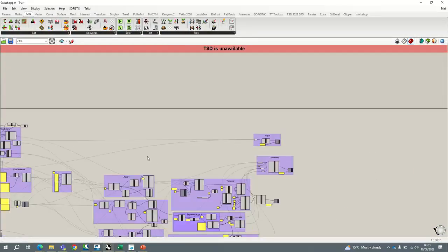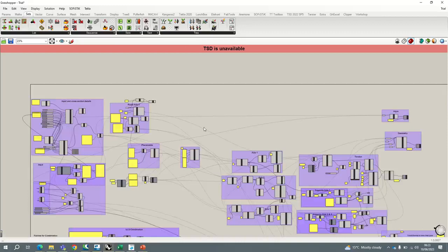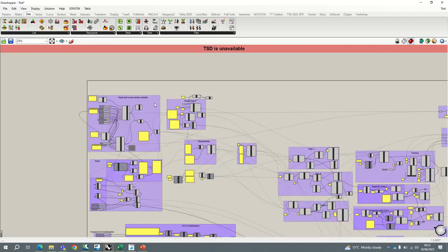So basically, I was working on post-tensioned I-girders and pre-tensioned I-girders. So this is the script which I have generated, which will automatically model the whole cross section in the geometry, the bearing orientation as well as load combination, and do the analysis for all those things.